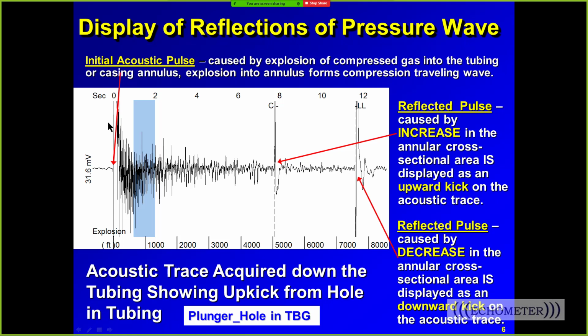And if you can't count the collars by shooting down tubing, sometimes you just have to use the gas gravity and the average pressure and temperature in the well to get the acoustic velocity. But usually you can count collars if the well's quiet and it's not too much liquid shooting down the tubing.